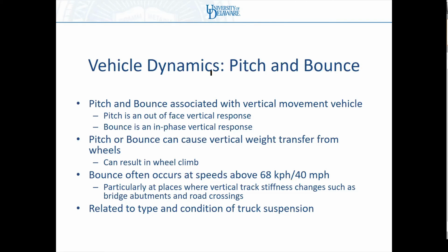Pitch and bounce, and again, the movie showed a pretty good example of that. Pitch and bounce happens when I have square joints, which is more common in the UIC world. So I have square joints, my joints or my welds are opposite each other.